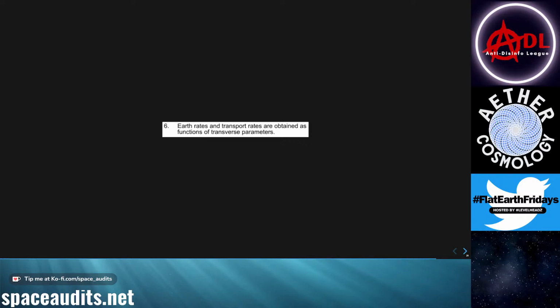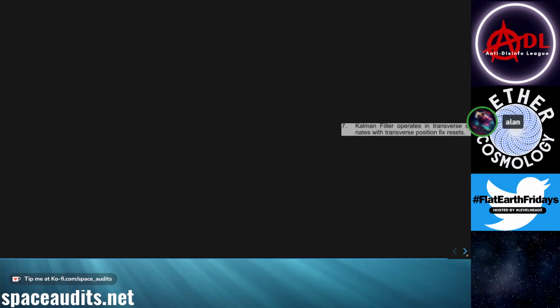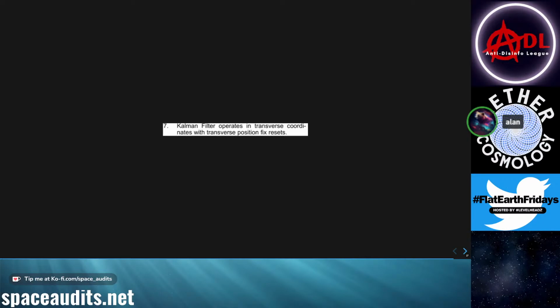1 second. Let's say we have number 6 here. So Earth rates and transport rates are obtained. Again, this is just keeping everything in alignment with the velocity stuff. Then 7, the Kalman filter operates in traverse coordinates positions to fix resets. So it backs up everything in regards to if they have to do a reset for the drifts or whatever. It'll always back up to the relevant spot on the reference geoid.